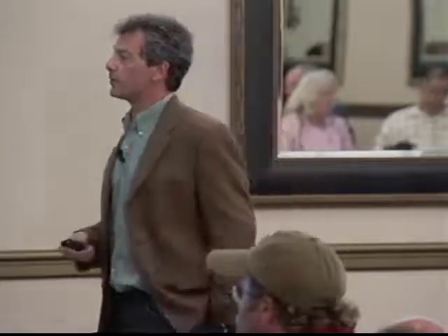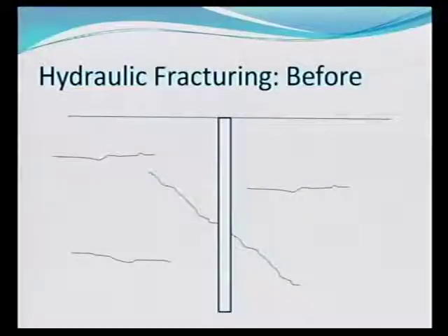Hydraulic fracturing can be done in much deeper systems. So you can drill a well and then hydraulically frack and increase the permeability. And this is done all the time in the oil industry and the gas industry, where they drill a well and they pump fluids in, and that causes a hydraulic pressure in here, and it can propagate fractures farther out, actually create new fractures, and it can cause connections in fractures.